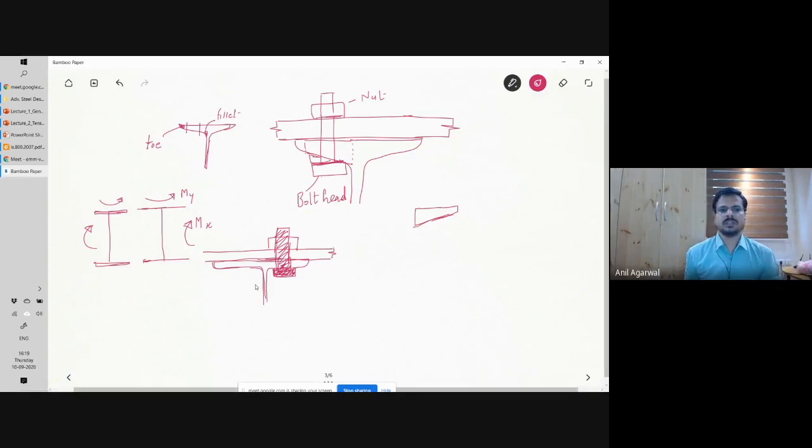When you are going to use it as a beam, of course, this is a more desirable behavior, because why would you want to waste material by providing more flexural rigidity in the minor axis? You are not going to use it in the minor axis so much. But if you are using it as a column or as a pile, then there are issues of buckling and so on. And for a pile, you need a greater surface area to develop more friction. For all those reasons, you may require a decent amount of width.